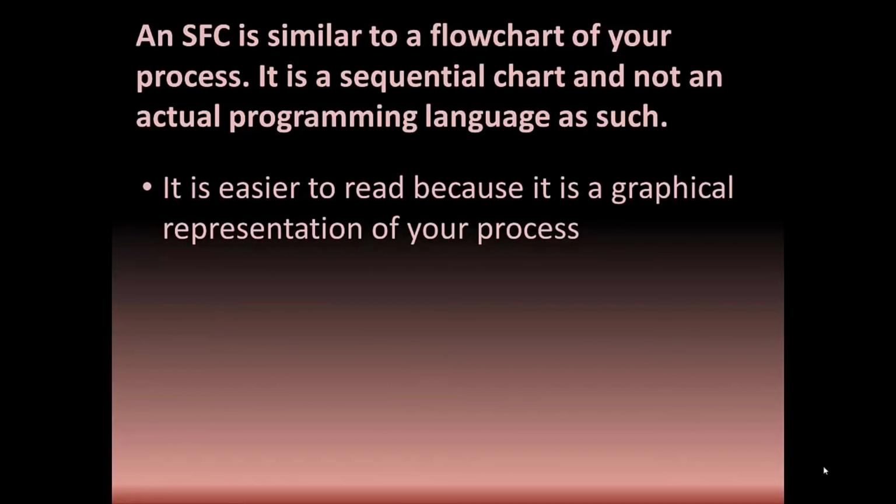If you cannot sit down and make a flow chart of your process, then you don't want to use sequential function charts for your program. If you can't easily chart out your process into individual activities that are not necessarily interdependent on the others, then SFCs is not a good tool for your particular project.